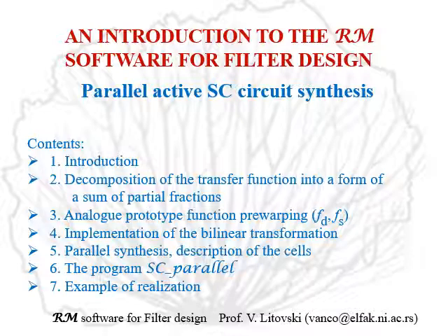Then we will speak about the decomposition of the transfer function into a form of sum of partial fractions, which is necessary for parallel realization. Then we will say several words about prewarping of the original or prototype function, which was the subject of discussion in the previous presentation.